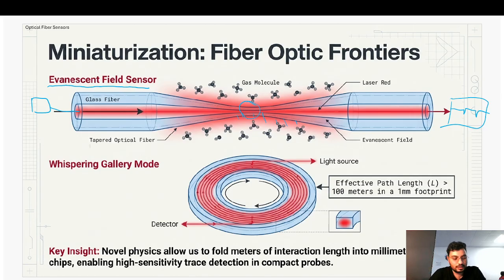And another thing is the whispering gallery mode, where the light is propagating in the cavity, and this cavity will be having circular light propagation. You can see here like this, and because of that there will be constructive and destructive interference, and we'll get the optical modes, and those optical modes will be having very high Q factor if you are using the proper cavity.